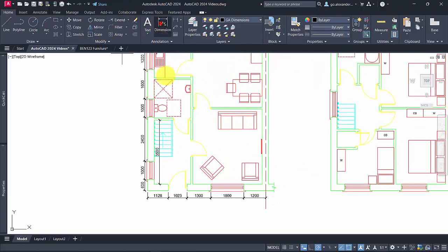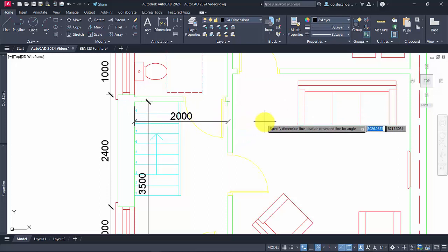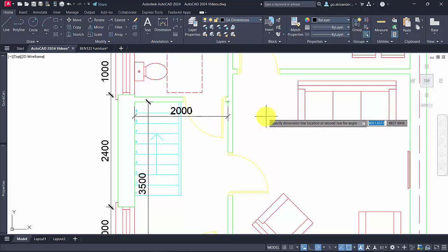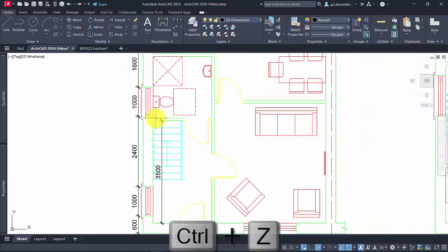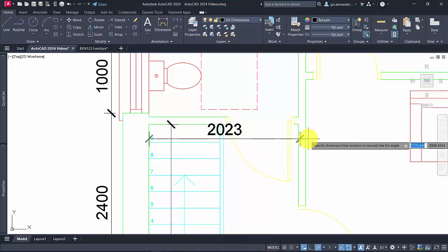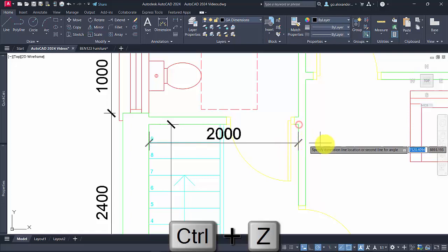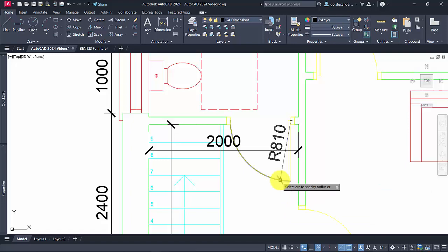The next dimension then, the width of the hallway there. So again, we want to move it down. It's not giving me the dimensions in proportion to where the endpoint is, unfortunately here, but stair treads are about 220, so I would say maybe 350 down. Again, things just aren't working out quite the way they normally do. That's just typical whenever I'm recording a demo as such. Make sure the cursor's in the right direction. Let's try 350 again. That's better.